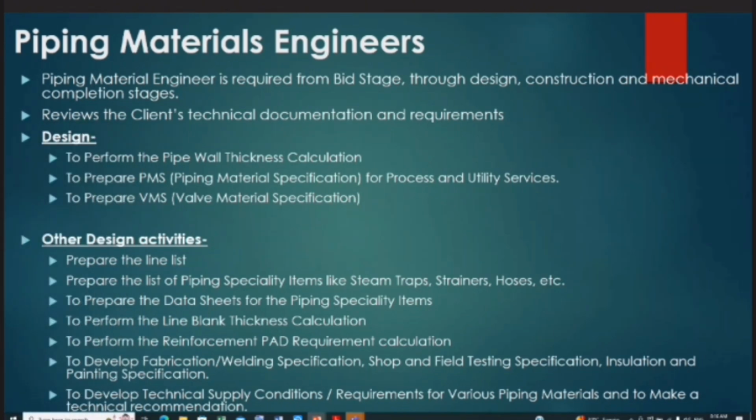Okay, and also the piping material. Engineers in a few companies assist in taking the piping MTO, or in a few companies there is a separate team for the piping MTO. Those piping MTO designers or engineers will take out the quantities of the piping components like pipe, valve, fittings from the PNID, and all this data will be consolidated by a piping material engineer in different softwares.